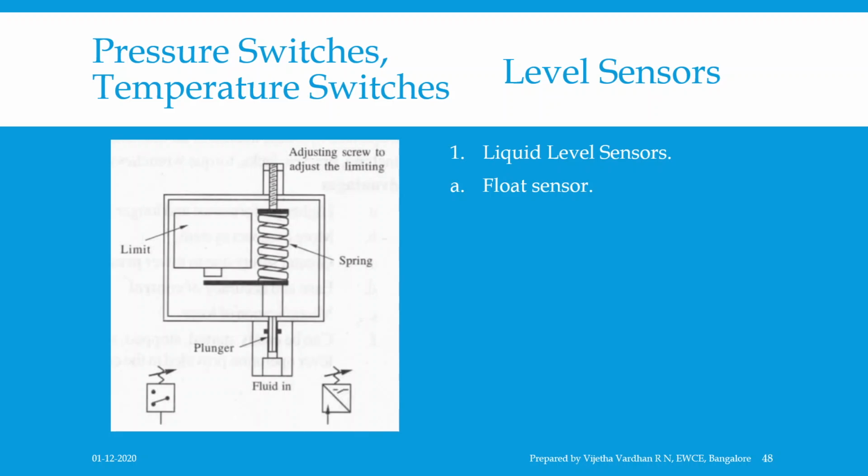The purpose of a float switch is to open or close a circuit as the level of liquid rises or falls. Most float switches are normally closed, meaning the two wires coming from the top of the switch complete a circuit when the float is at low point, resting on its bottom clip. That is nothing but an example you can consider when a tank is dry.